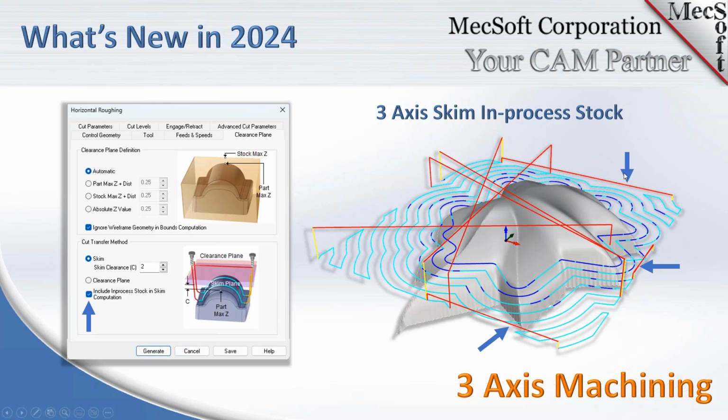So if you look at the arrows over here, you'll see that in the areas where the tool had to traverse above the part, it applied the Skim clearance to the highest position on the part. But if it didn't have to span over the part, it calculated the Skim clearance based on the cut level. So if you see these small retracts right here and over here, that's what happens when you have this checkbox checked. This is just an enhancement to help you maximize your machining time.